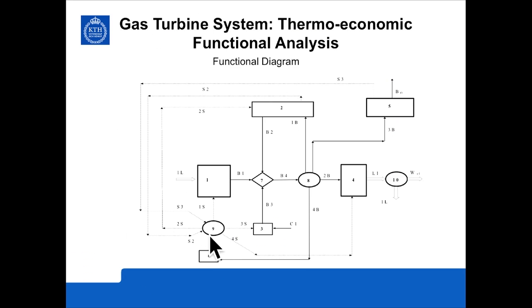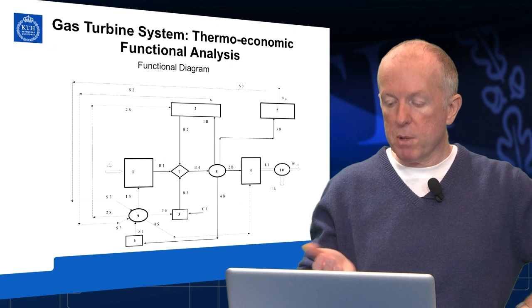The net entropy flow produced by the external environment is afterwards distributed to all the components producing entropy, as we said. So it is distributed to the air compressor, the air preheater, the combustor, the gas turbine, and you also see in this branching unit you receive an input in terms of net entropy from the heat recovery steam generator, because remember, part of the role of the heat recovery steam generator is to dissipate the entropy accumulated in the exhaust gases.